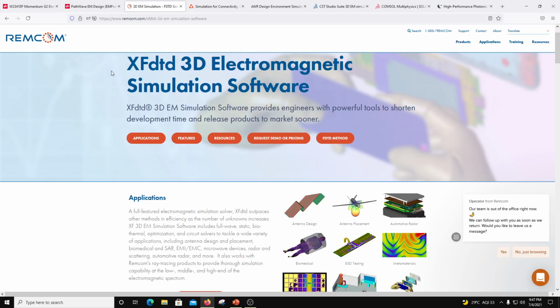Okay, so that there are no ripples reflecting back into the space. The same anechoic chamber concept is there in FDTD, which is absorbing boundary conditions. These absorbing boundary conditions are made up of cells of certain thicknesses. For example, the boundary may be a 3 cell thick boundary or a 5 cell thick boundary. So that adds additional space in computation, and the material defined in these cells is going to be highly absorbing material.